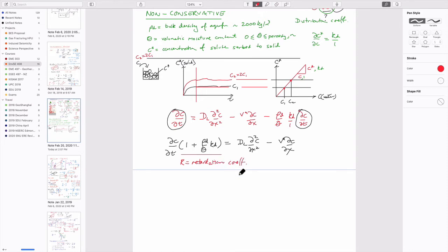In other words, as you'll see in a moment, how much the concentration is retarded, delayed in arriving, and also how it's attenuated somewhat. And so if we write this expression out as change in concentration with time times retardation, plus the dispersive part, diffusion and dispersive part, I don't want to belabor these equations because it's what these equations mean that's important to us.